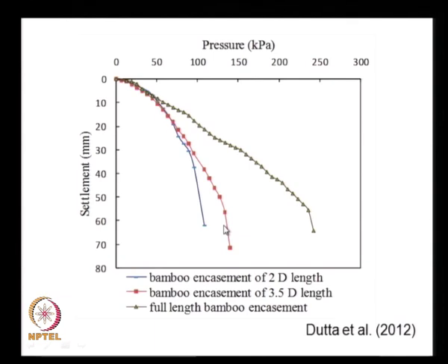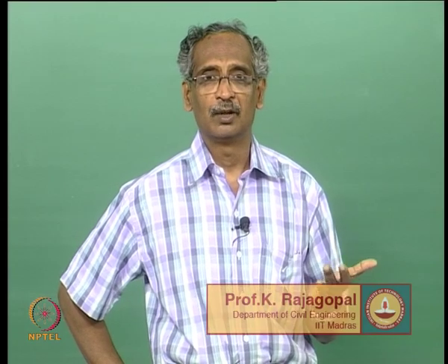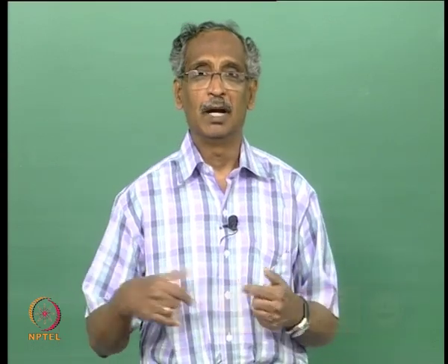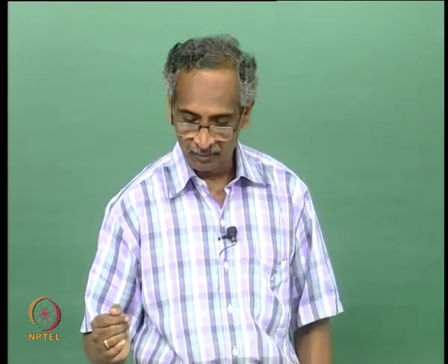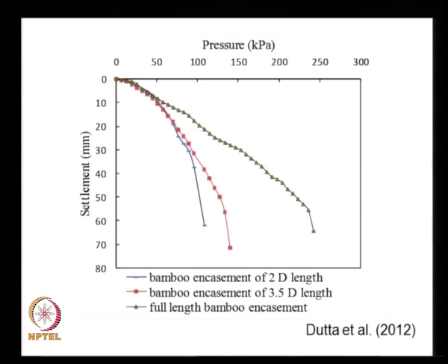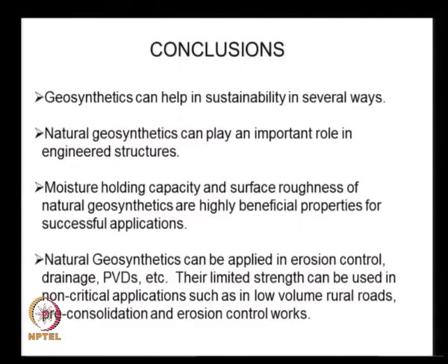So, that means that even bamboo reinforcement can increase the stone column capacity, and wherever we need the stone column support for a limited period, then we can utilize bamboo as a possible encasement to improve our stone column stiffness and also the ultimate load capacity.